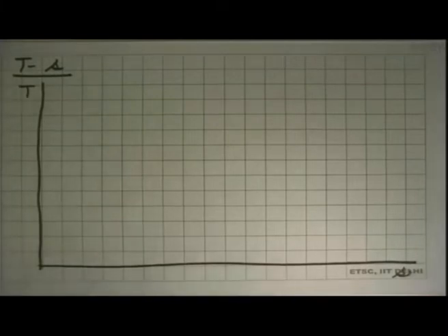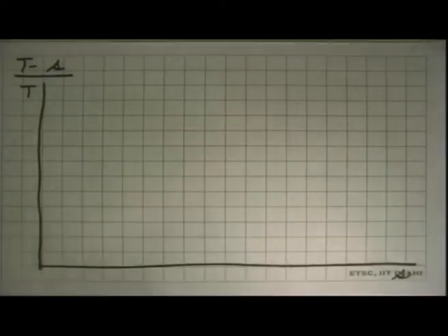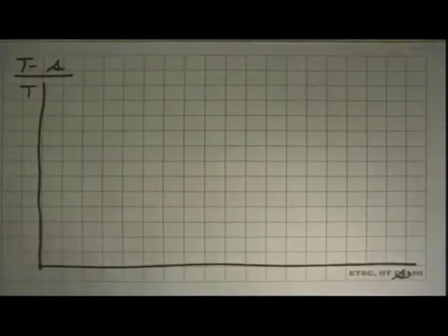And again, making this plot, you have to have the same caution that we had with the p-h plot. Once you have set specific enthalpy at a particular point to 0, specific entropy also gets set to 0. So specific entropy has the same issues, that specific entropy of nitrogen has got some value, specific entropy of water has some value. The two are not on the same scale. Temperatures are on the same scale, specific volume is on the same scale, but specific enthalpy and specific entropy are not on the same scale. We have to have a common reference point for everything, only then we can compare them.